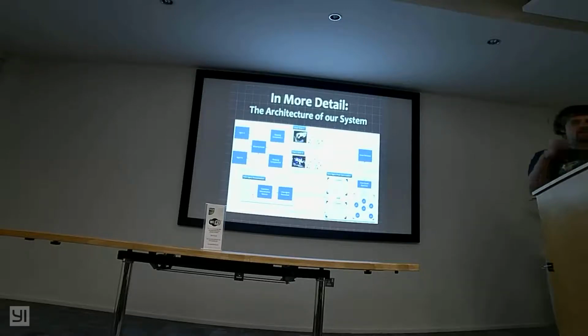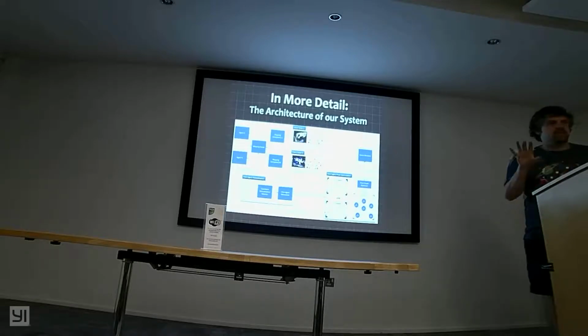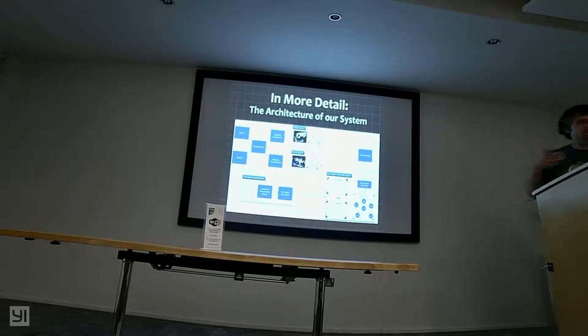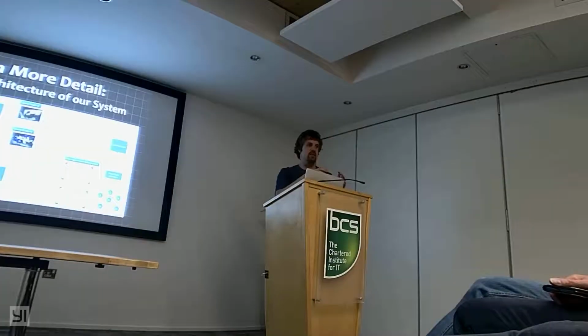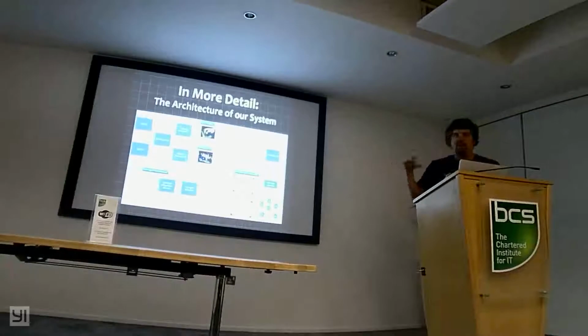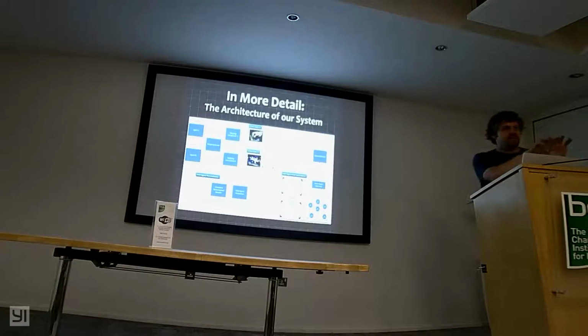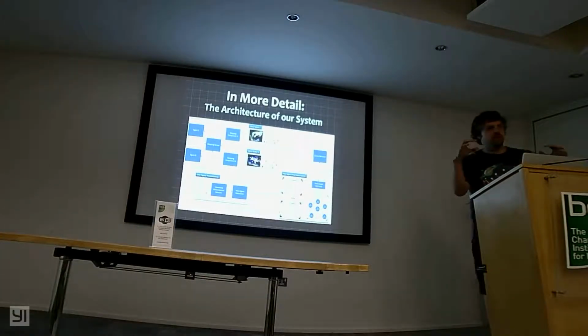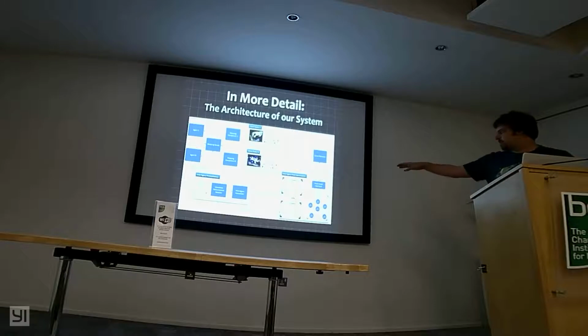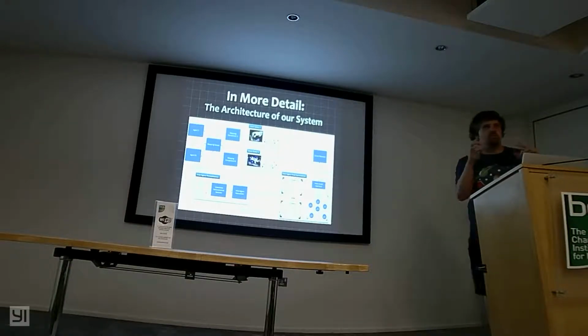Basically, the issue is which image from a particular scene do you feed to the other one. One thing you could do is, as you're going around with the individual agents, capture a sequence of images for each agent, store those, and then pick one later and relocalize it against the other scene. In practice, that would take huge amounts of memory and doesn't scale very well. So what we actually do is store the trajectories for different agents, and because we're reconstructing 3D models of the individual subscenes, later on we pick a pose from the trajectory of a particular agent. We render the model of its scene from that pose, take a synthetic image, and pass that to relocalize with the other scene.